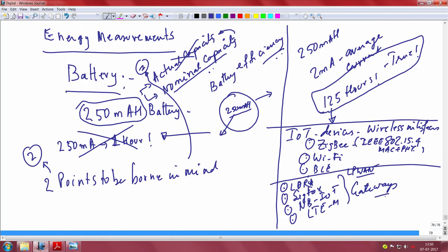These are all for gateways, right. Why am I saying all this? I am saying this because you may have to consider how do you want to drive these gateway devices and how do you propose to drive these little access devices, small little devices which have sensors. So it has an impact. Most often the gateway devices, I do not think you will be able to drive with small coin cell batteries and so on. It is not going to work. You must need either very large batteries, or you should end up with connecting it to the grid supply, right. So these are the two things.